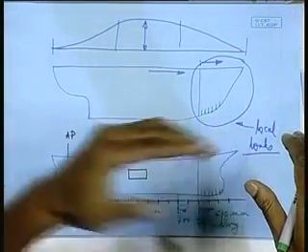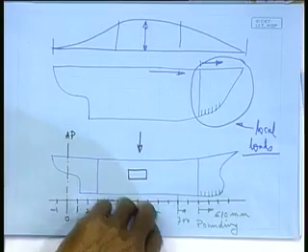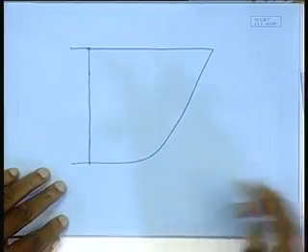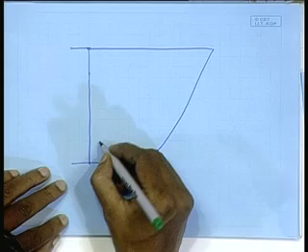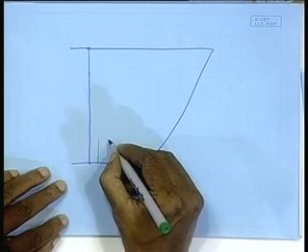In forward, I will give a plate floor at every frame position. Like I said, in the engine room, at every frame position I give a plate floor, because heavy load is coming. Here heavy local load may come, right. In addition to that, what we will have here is at every frame location you will have the plate floors.